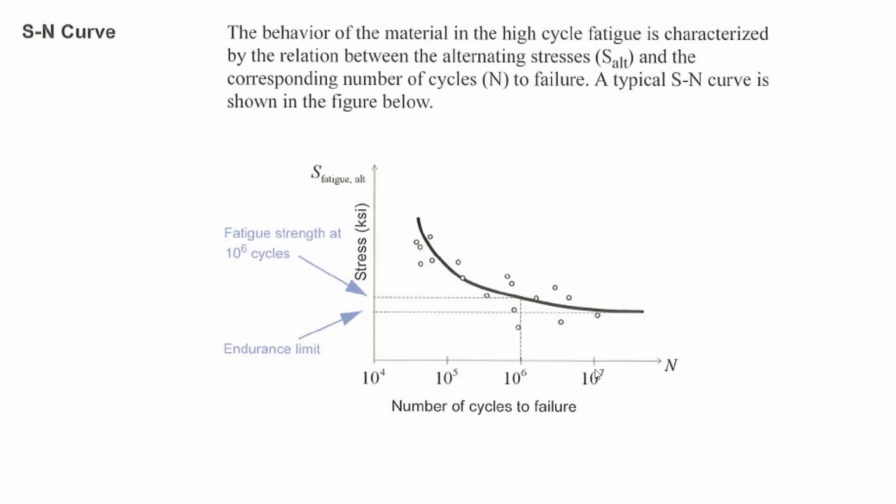So we can consider, if your component has the fatigue cycle more than 10 raised to 7, your model will be safe enough. It has the higher lifespan, so unlimited lifespan we can consider. So these are the approximation points you could say. This is the practical testing we can consider. Depending upon that, this curve will be drawn with respect to approximation.